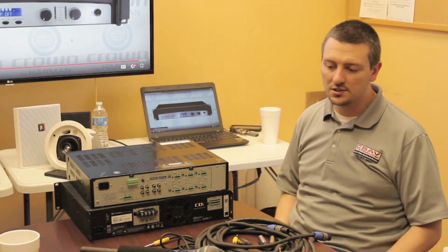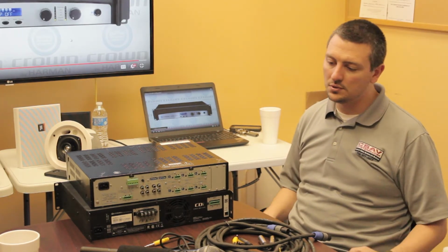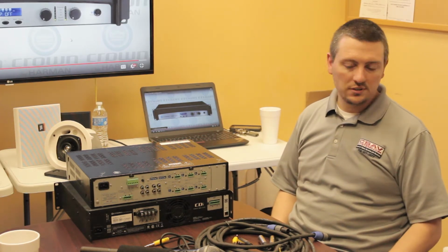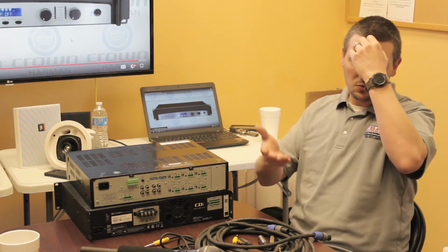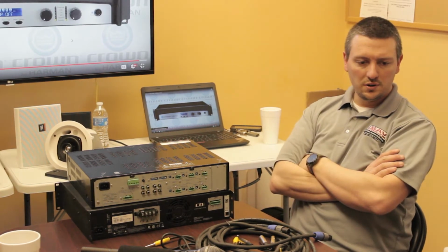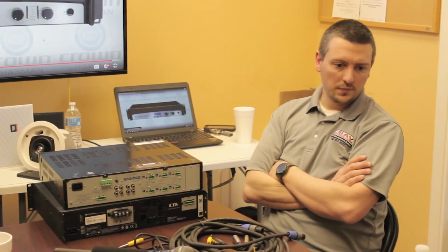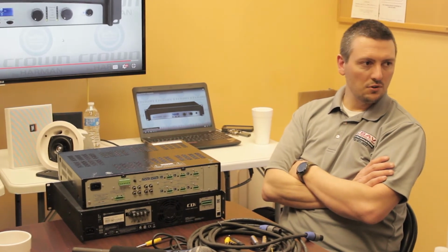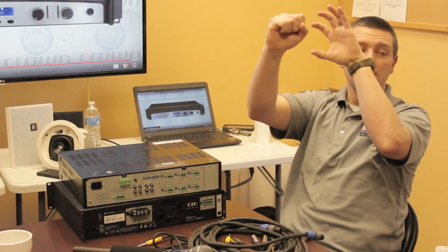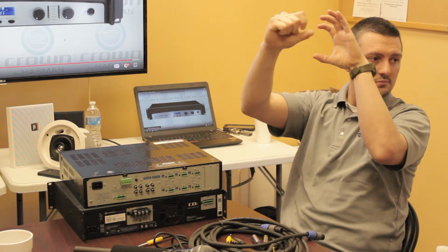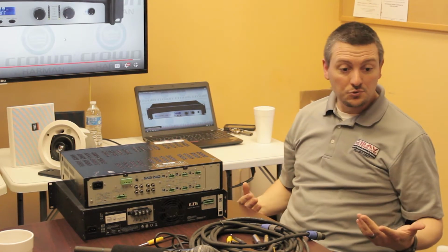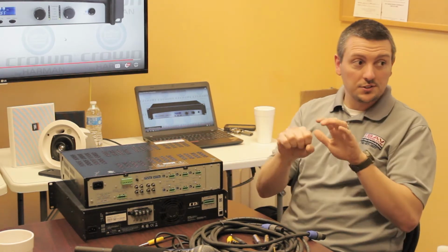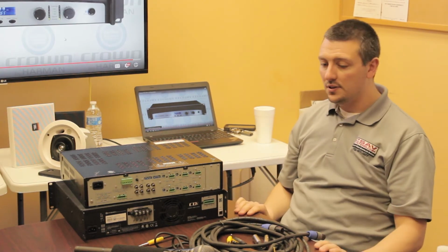And terminations, take your time with terminations. Don't just jerry-rig things, and make sure things are connected. A couple days ago, we were at a job where a guy's camera wasn't working. So I go up, I take the camera off, and right behind the camera, it was a network camera, the RJ45 wasn't plugged in. I would assume that it was plugged in initially, but it just didn't snap in.